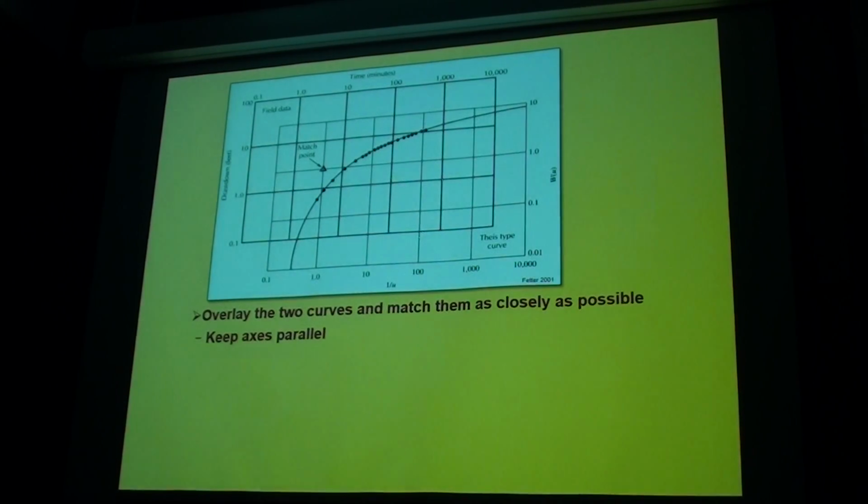So here's the two overlaid. Here's our type curve, this nice one here, 1 over u against W(u), log plot. This here also is a log plot. There's our drawdown, that's s. There's our t, little t, time, in minutes, days, seconds, whatever you want, as long as you keep it constant, as long as you're aware of what it is. As you can see, this pump test data fits nicely along this part of the curve, just here. But the two graphs are offset by a bit of a margin. Right? Well, that's really useful for us.